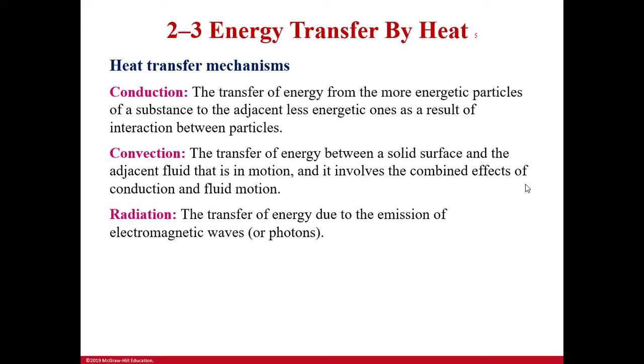Conduction, convection, and radiation. Conduction is the transfer of energy from the more energetic particles of a substance to the adjacent less energetic ones as a result of interaction between particles. Convection is the transfer of energy between a solid surface and the adjacent fluid that is in motion. So convection has motion in it, and it involves the combined effects of conduction and fluid motion. Radiation is the transfer of energy due to emission of electromagnetic waves or photons. No conduction, no convection here; energy is transferred through emission of electromagnetic waves.